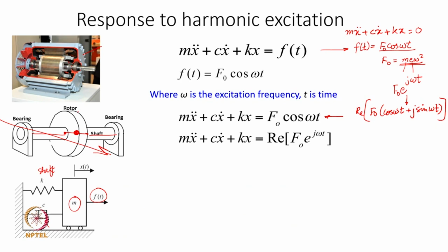Systems are typically considered linear when the amplitudes are small enough, so that the restoring force to vibratory displacement relationship is linear. So, your constants m, k and c, these elements of the vibratory system, have constant coefficient values. As long as they are constants, the governing equation of motion is linear. So, with that assumption of a linear vibratory system,